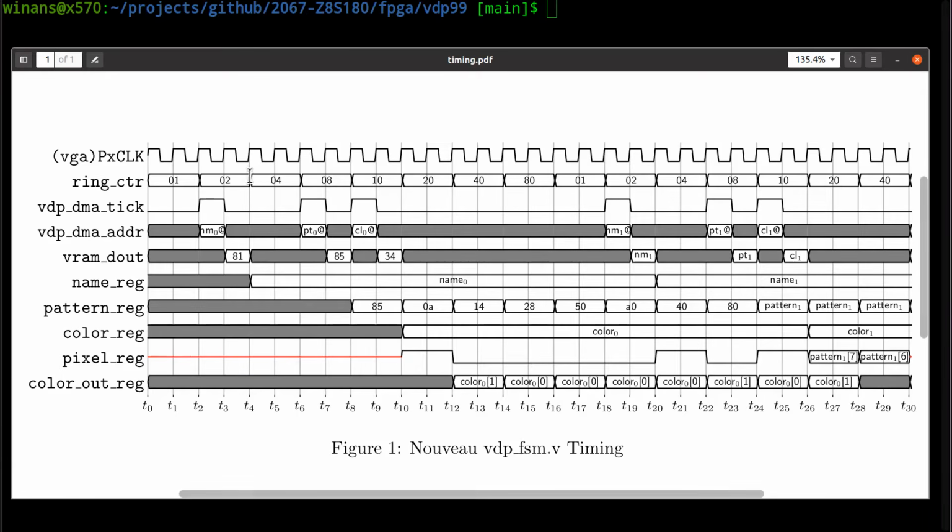All right. I want to point this out because we'll see it in the test bench waveform. You'll see these delay FIFOs in there. It's not a big deal. It's just, if this thing is going to generate the color pixels 12 time ticks after the VGA sync module wants them to be output, then we have to delay the other signals to go along with it, so that the sync and the borders and all that happen around where the color pixels are going to come out due to this delay. Okay, and we'll see that in the code as well.